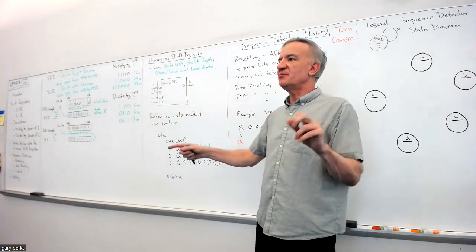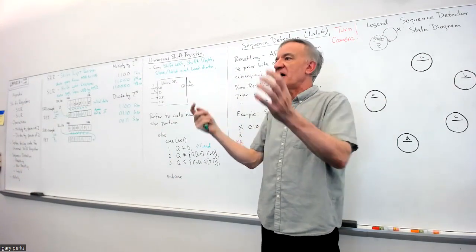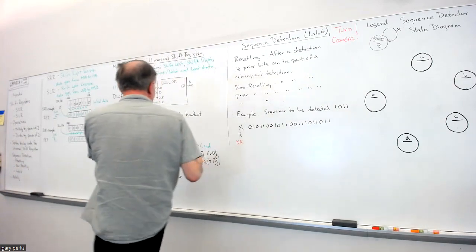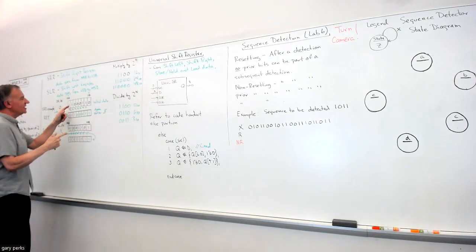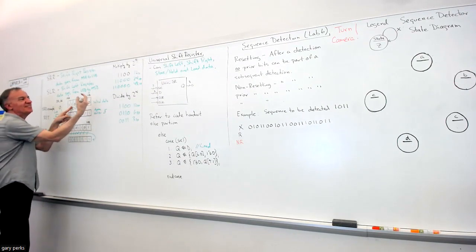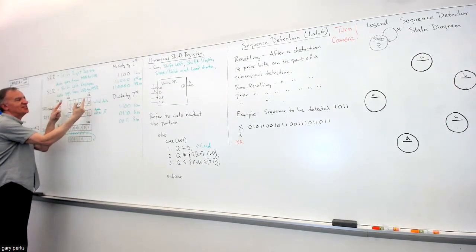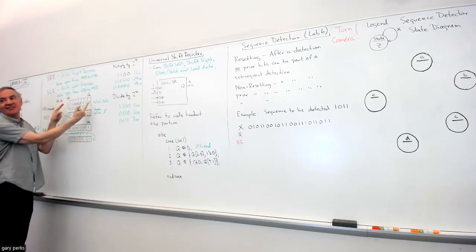Concatenate. And concatenate means you're just putting stuff together, right? Combining, joining. So you see what's happening here is it's taking these 7 bits and then it's attaching a 0 to the end. So effectively, what happens when you do that? When you take these 7 bits and you put a 0 on this side, it's all going to fit within this 8-bit register.